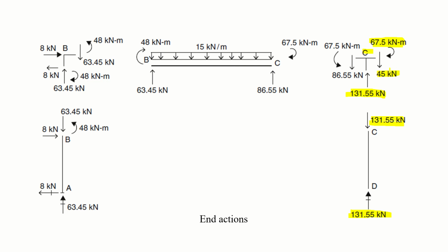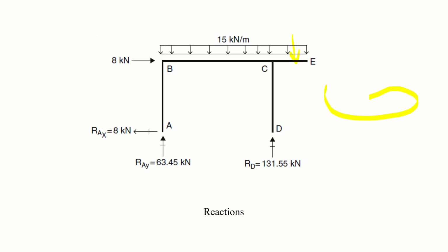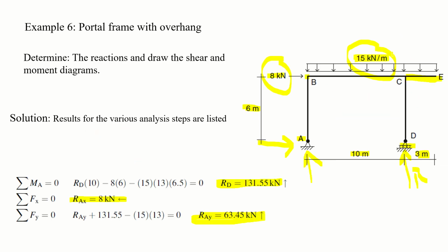You have to balance these three on this beam side, because you are going from the weak side to the stronger side. Let me show in this figure that this is the weaker member as compared to this one, and this is the weakest member. So at joint C, you take the reaction from here and the reaction from here, and you balance in this member because it is going to the stronger support.